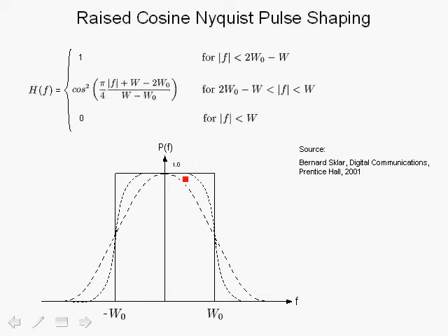In between, we have a class of filters that can be changed by specifying different values for W and W sub 0. W0 is a frequency about which all of these filters that you show over here exhibit a symmetry. And this is a key requirement, as we will discuss. Having symmetry about this point ensures that in the time domain, all the impulse responses of these pulse shaping filters would have zero crossings at fixed periods. We'll show that in a minute.